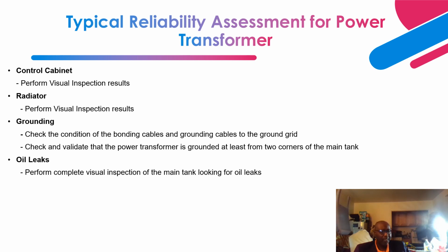As you know, for a radiator, the butterfly valves are located right at the top and the bottom, because that is where the hot oil from the transformer enters the radiator. After convection action, it rises to the top and through the radiator. The radiator takes the heat away, and so the cooler oil comes down and goes through another butterfly valve back to the main tank.